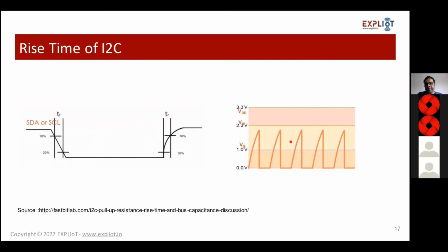But when you get a negative acknowledgement during I2C communication, always check those basics. Is your pull-up resistance within the limit? If you put it too high, things will not work properly over a period of time, and this becomes worse if you have multiple slaves.